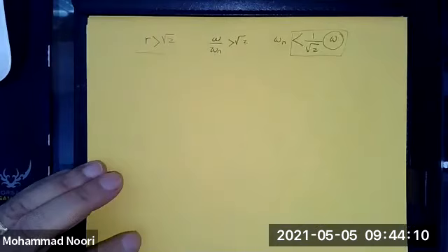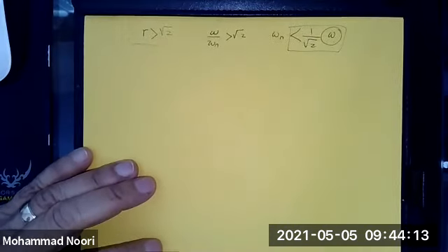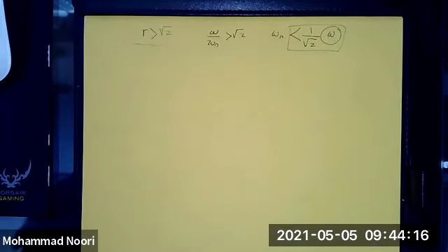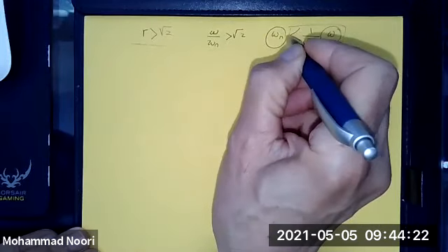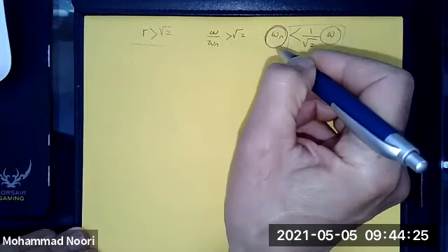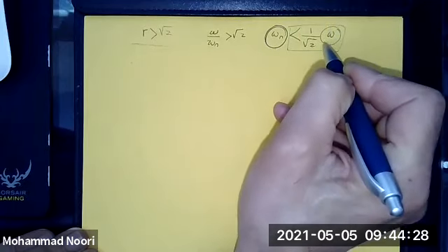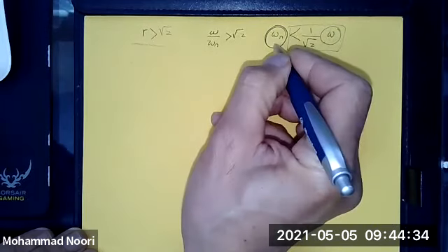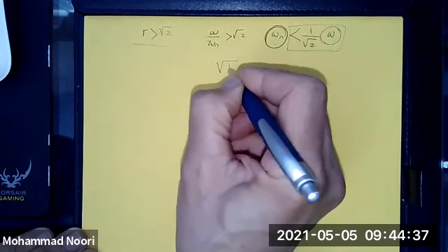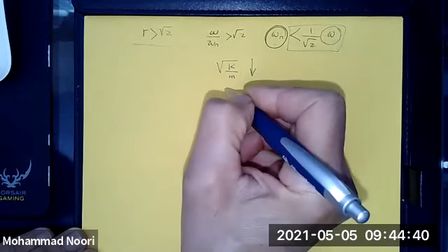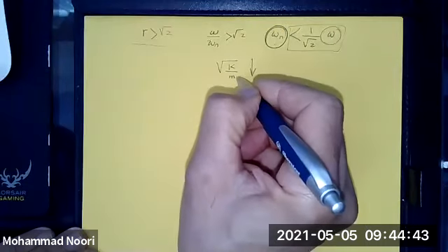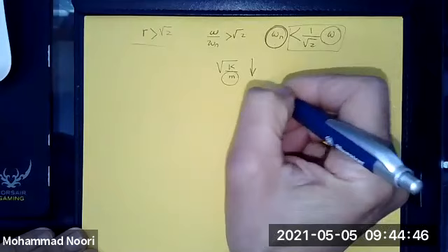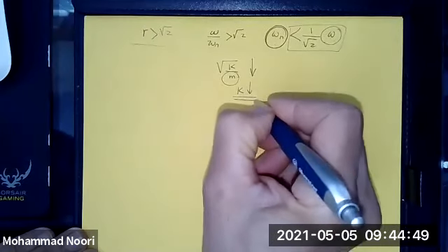But if you don't have control over the forcing function, and you want to design a support structure to support a rotating piece of machinery, that means you need to design that system such that its natural frequency is less than this. Or in other words, you need to reduce this as much as possible. You usually don't have much control over the mass, so that means you need to reduce K.